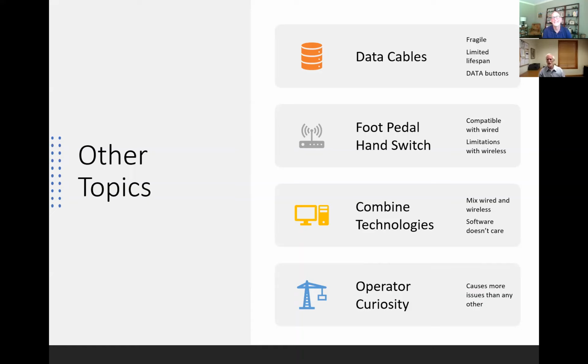The other thing we have is people that want to share data cables between different gauges because they're compatible with the same cable, a Mitutoyo caliper cable, for example. So they're plugging and unplugging them. And these are not durable connectors. There are 6 brass leads on them and a plastic housing. We've seen the plastic broken off and the leads dangling. We've seen the leads bent. But just one thing to be aware of is these cables are not designed to be abused.